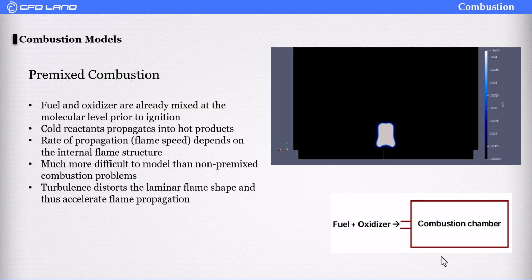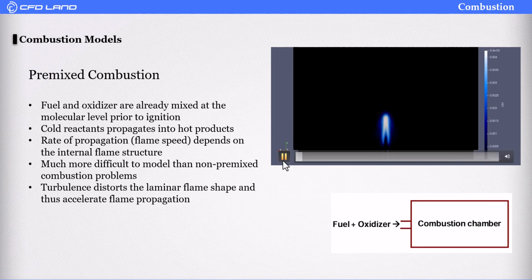The limitations of this model are that it must use a pressure-based solver. It is valid only for turbulent and subsonic flows. It cannot be used in conjunction with the pollutant models, and cannot be used to simulate reacting discrete phase particles. Here we have a simulation in OpenFOAM that shows temperature for the flame.